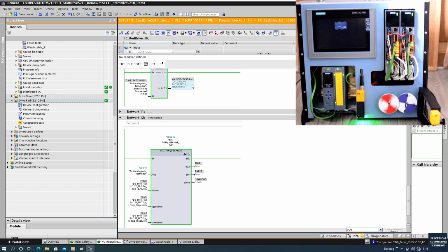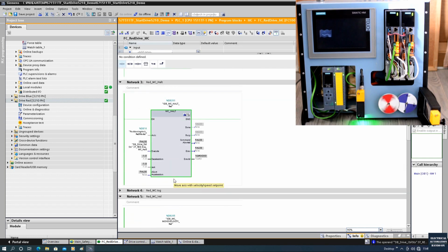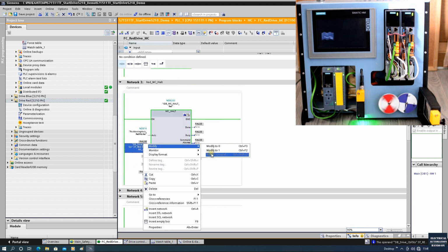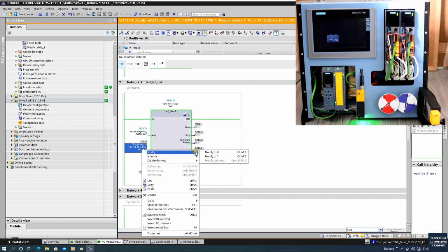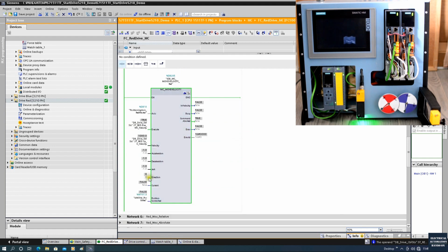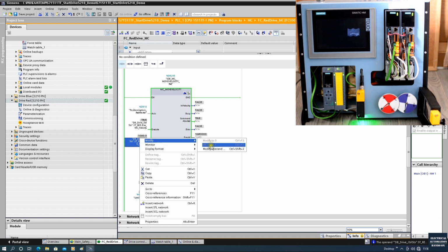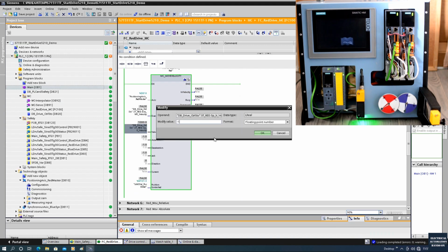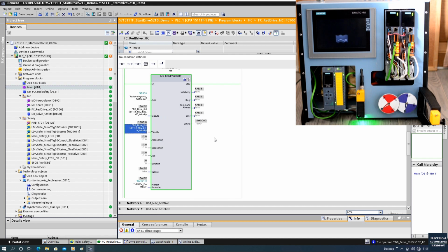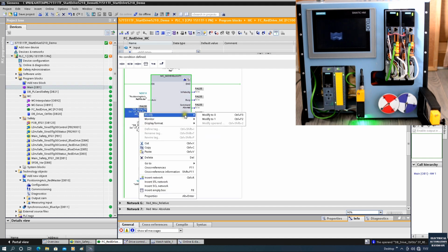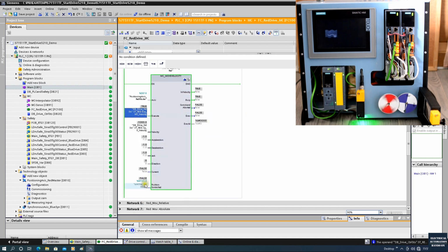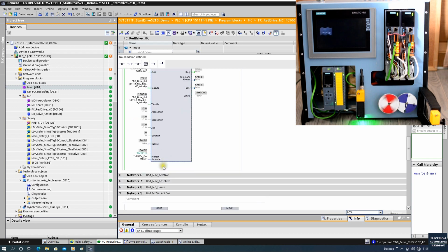Okay? Then, for the backward direction, now I will first stop the motor. Let's halt the motor. And this time, I will run in a backward direction. So we'll still leave this position control off. Okay? And I will set negative 1080. Okay? And then I will trigger again.